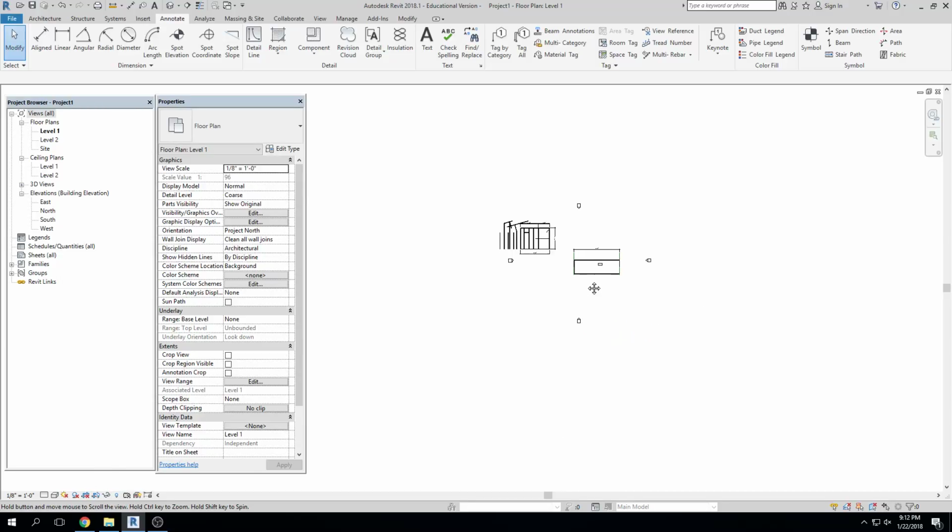I want you to remember that within Revit we have a crop region, right? If this crop region doesn't show anything, and I crop it and turn it off, you may open up a drawing and wonder, where's the drawing? Where's the building? This can happen when you're working in an office. Somebody has cropped something out because they don't want to see it while working on something else, but they say, hey, get in this file and do these things. You open it up and wonder, where's the file? I don't see the extent of it. I can't see the other property line. Where's the parking lot you're talking about? And it's so easy to do.